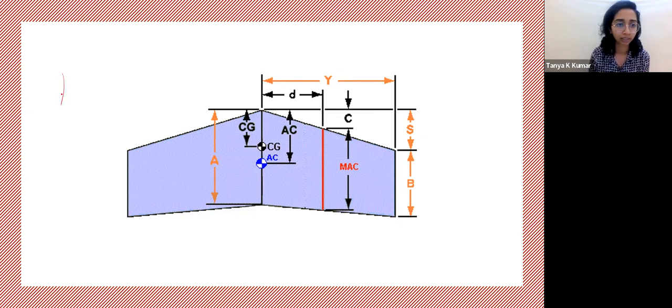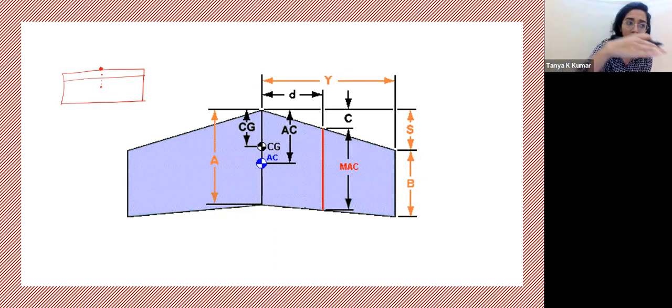So if you have a rectangular surface here, at this point when there is no weight added, your CG is at the middle. Now, if you keep adding weight ahead, at some point your CG will go ahead of the aerodynamic center, which is usually at the quarter chord point. So the CG moves ahead and at some point it will cross the AC. At that point, when you try to fly this plain sheet of thermocol, it will not tumble, it will smoothly fly. You can just try this at home.